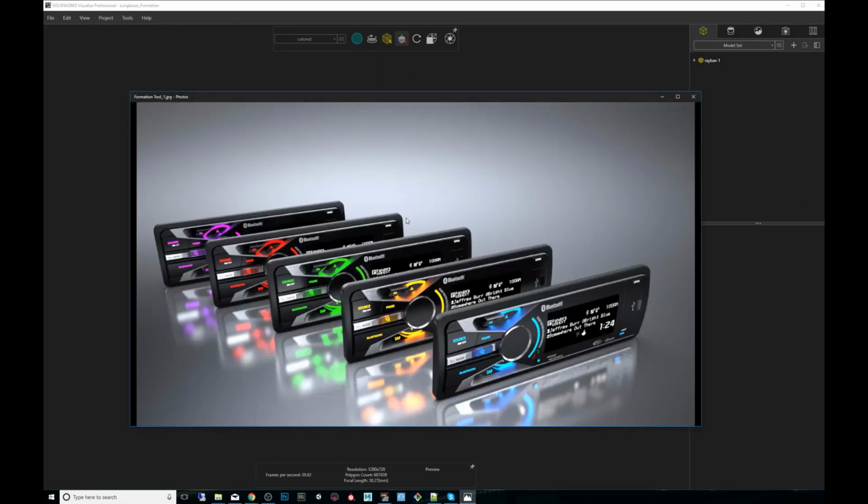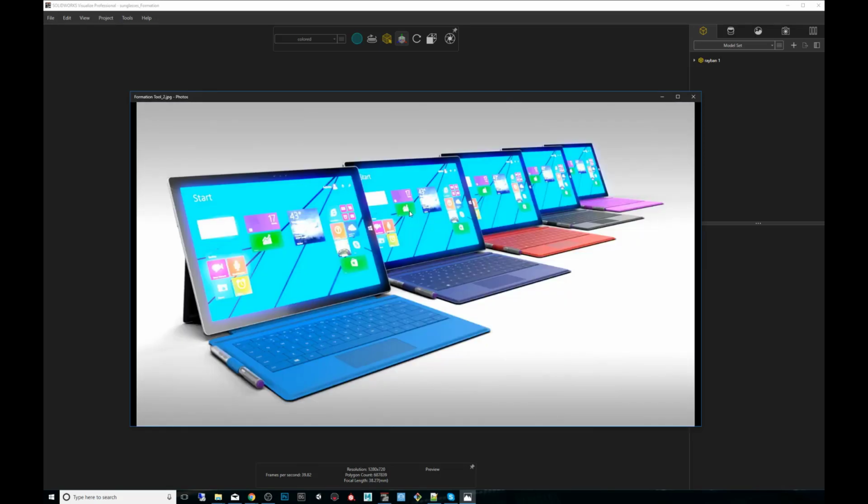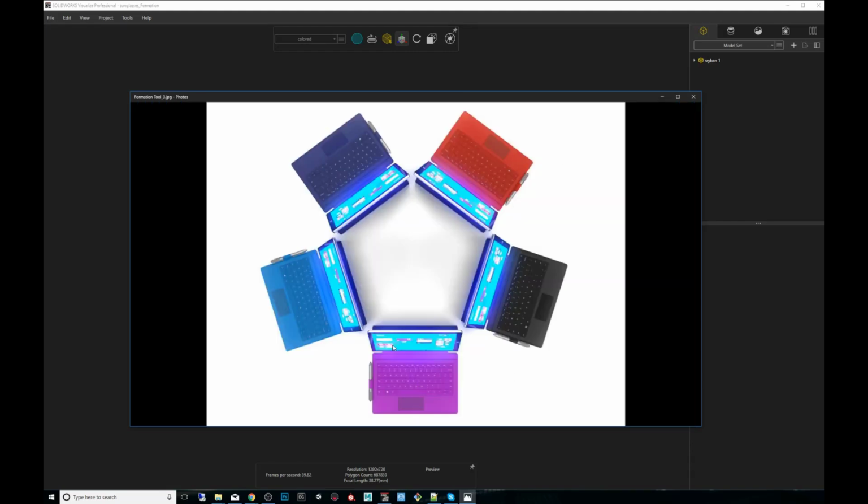You can see these are all the same models and they're laid out exactly apart from each other. So this tool allows you to do exactly that. You can do that linearly, diagonally, in the shape of a V, or in a circular shape pattern. So you can see here we have the same model, and it's showing off different textures, different colors, different materials. Same from above, and that's really the power of this tool. You can do this very quickly, within a few seconds, really, and lay out exactly what it is you want to see, and set it up for render.